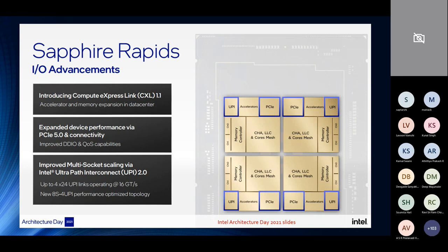For those of you who have seen computer organization, you can have a multi-core, multi-processor system where you have quite a lot of memory shared among those. The biggest bottleneck, or biggest headache, I would say in very simplistic terms, is the coherency. You really need to have coherent protocols defined for you to be able to utilize that massive amount of capacity and resource you have. You can keep on packing more and more cores, more and more cache, but unless you ensure that the coherency is maintained, there is no point in having so many resources.